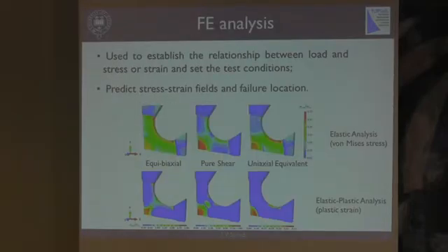So the first thing we did was to do some finite element analysis. We wanted to do this because the load ratio that you apply is not the same as the ratio of the stresses that you see because of the specimen design, and it's not the same as the ratio of the strains, and so we did some elastic analysis.